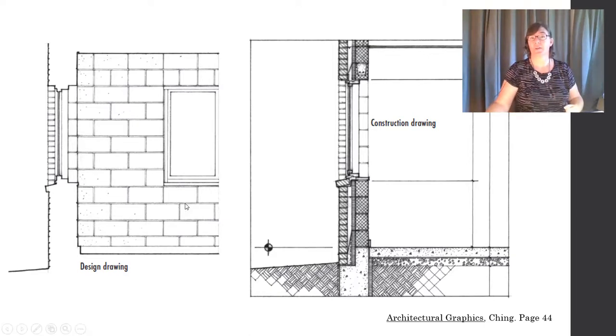In the construction drawing on the right, you can see also the items that have been cut through are a much heavier weight. We've got again some surface texture back here that is a much lighter weight. And finally, there are some dimension lines and extension lines that are of a thin line weight.